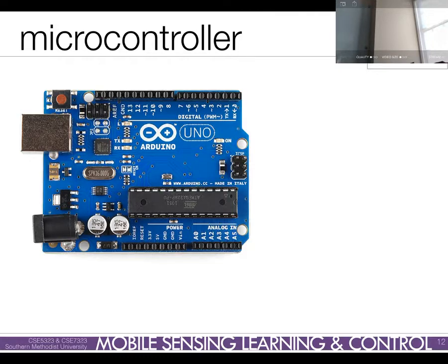That's the clock. That's a quartz crystal. It's running at 16 megahertz so that it can sit there and feed that into the microcontroller. Otherwise, the microcontroller doesn't have an onboard clock, right? Or it does, but it oscillates really, really slowly.